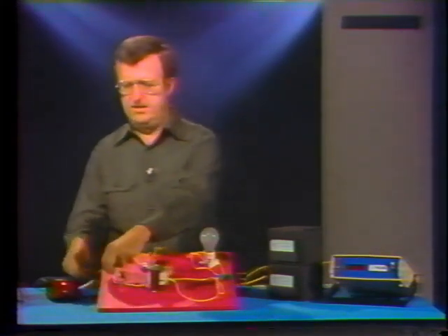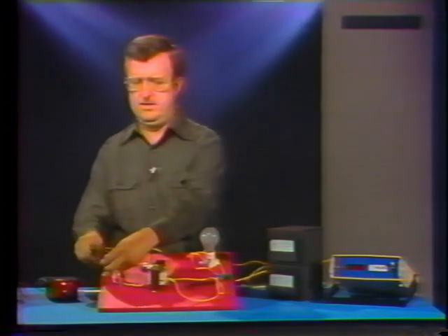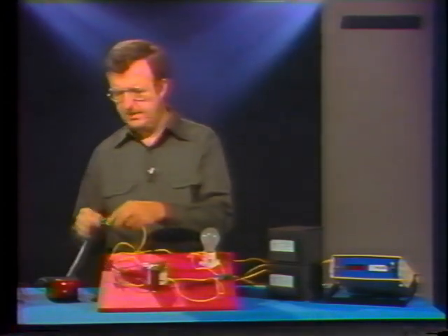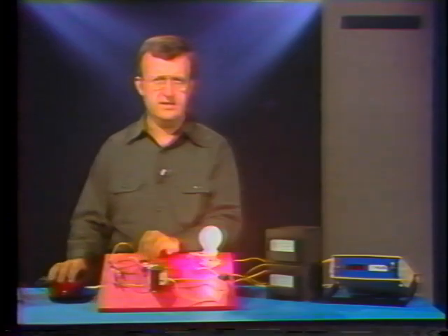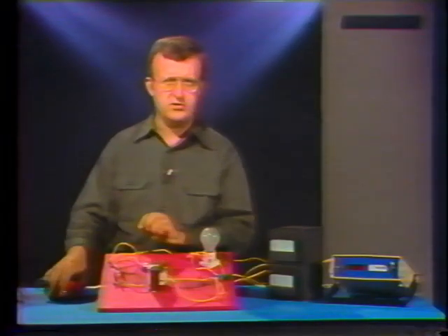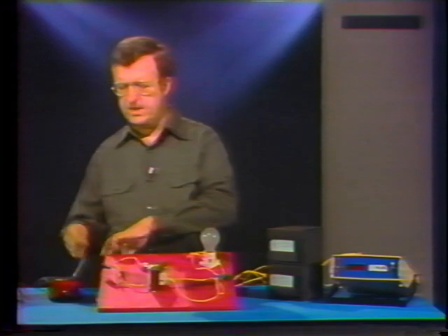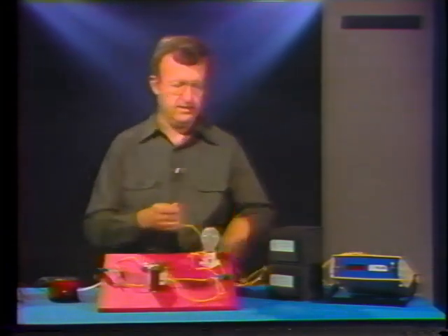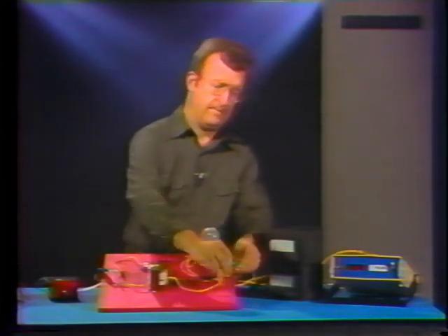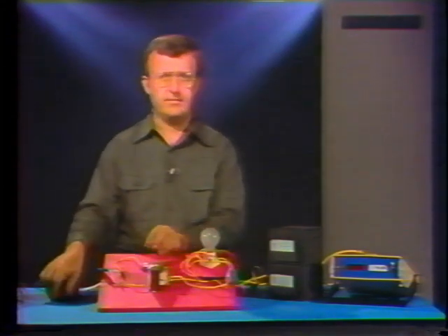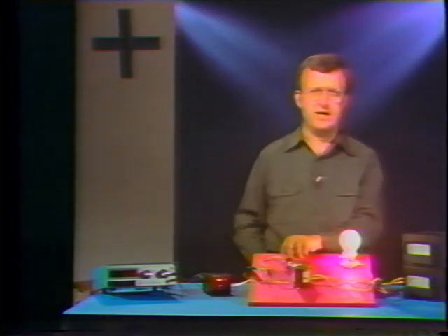Okay, first, we will measure the power that goes into the transformer. Okay, get it connected, on, and it's just about 24 watts. The power coming out of the transformer should be the same. We'll hook up the watt meter and measure that next, right over here. Now, we do, and it is also just about 24 watts. So we were right, power in does equal power out.